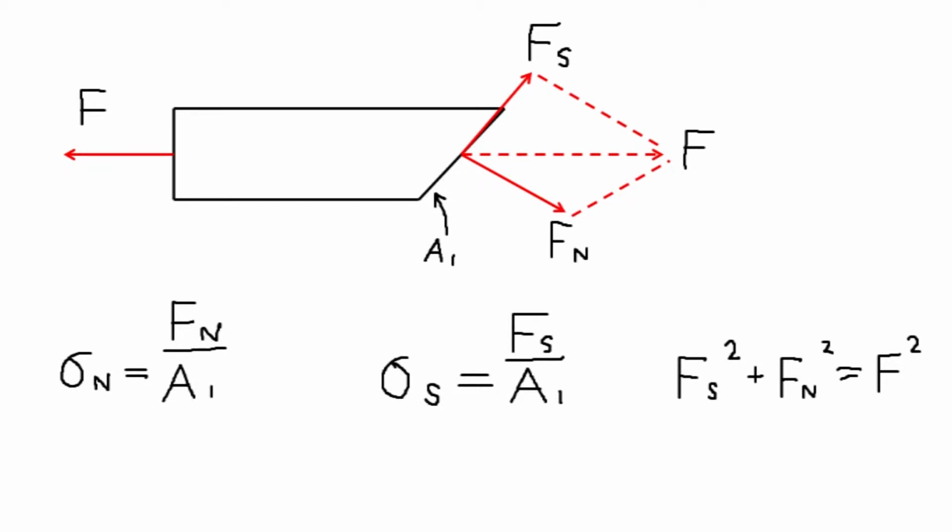However, when I go to calculate the stresses on that plane, I now have that axial force distributed over a larger area, and therefore the stresses change. In looking at a free body diagram, I have forces to equilibrate the axial force. I have a force perpendicular to the plane, assuming the slant plane is this way, and a shear force on the plane that goes along the surface of the plane.